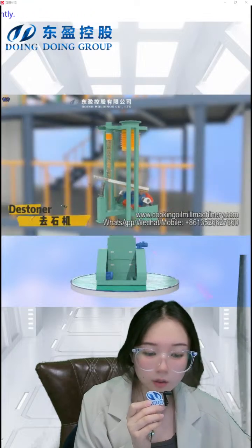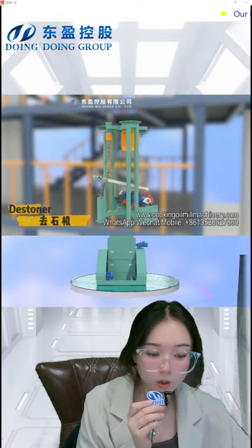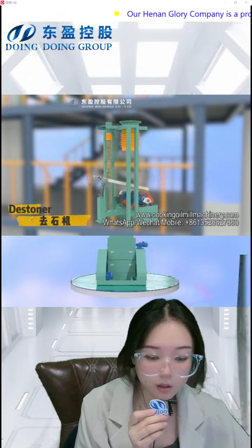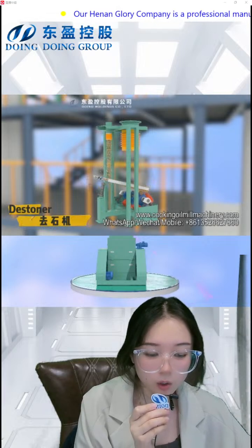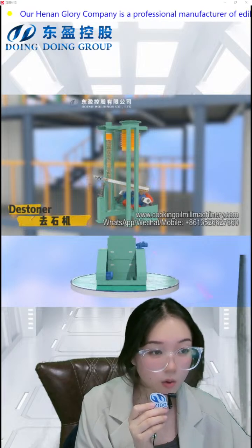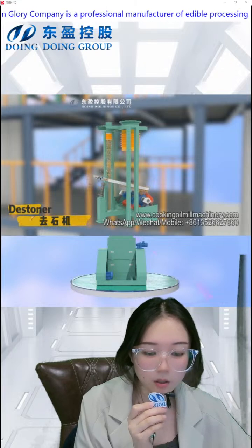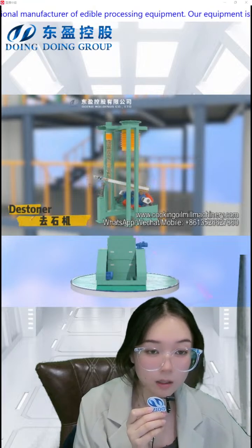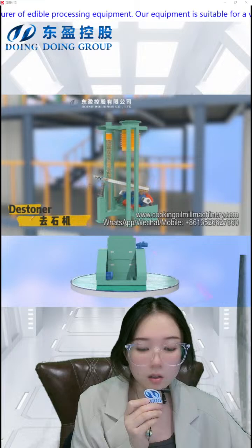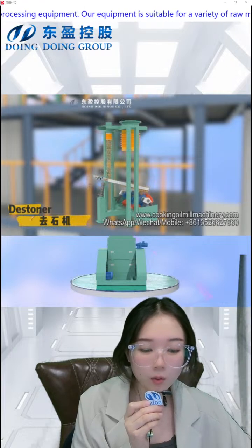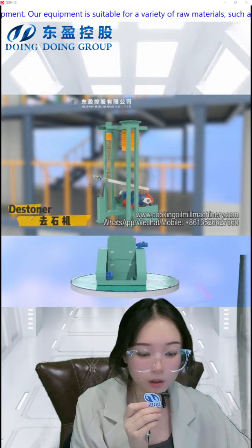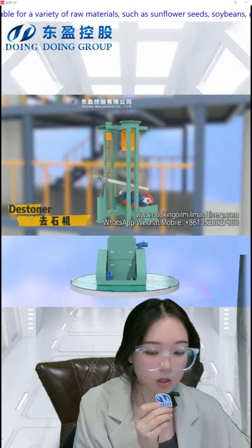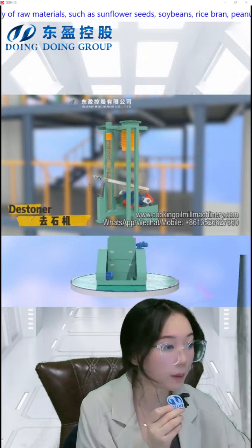In addition, for cotton seeds, a fan needs to be added to the cleaning section to remove the short fibers attached to the cottonseed shell. Through the rich project experience of engineers, and the strict control of the equipment quality in our factory, the impurity removal rate can reach 98%. If the impurity content is too high, a specially developed machine can be added.